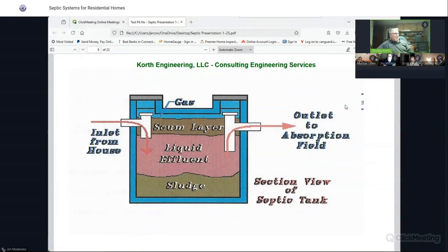It's kind of similar in some ways to a compost pile. What do you do with a compost pile every so often? You go and turn it to give it oxygen. If the oxygen gets deficient, the compost pile doesn't work very well. Well, the same thing with the leaching fields: if you put stuff down there, a lot of oils and greases or sludge that takes a lot of oxygen, that's when your fields typically start to fail.